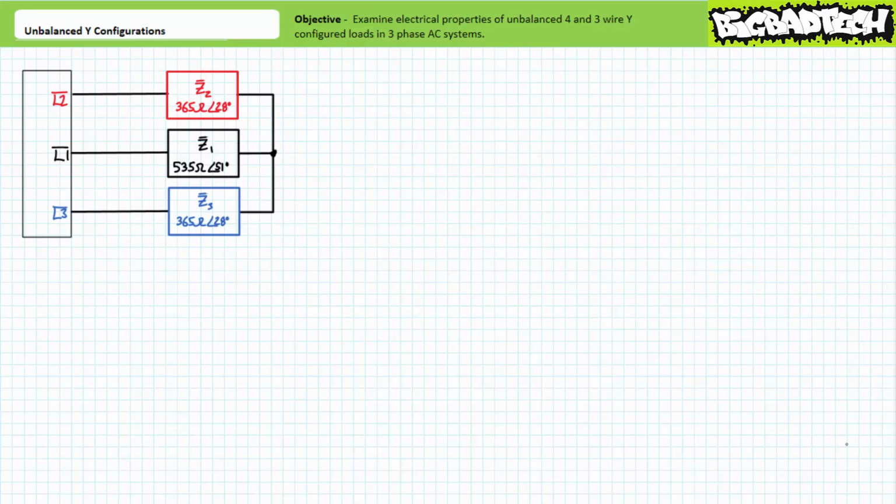Unbalanced 3-wire Y configurations necessitate a wholly different approach. As I previously alluded, load elements in unbalanced 3-wire Y configurations might not even experience the same voltage magnitude, to say nothing of current magnitude, relative phase shift, and apparent, real, and reactive power, principally because any imbalanced current is left to circulate throughout this system, messing it up along the way. This tiger not only has teeth, it's wearing a bulletproof vest and night vision goggles.